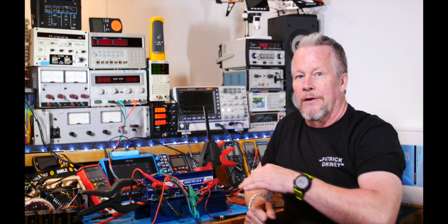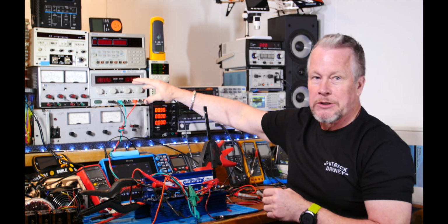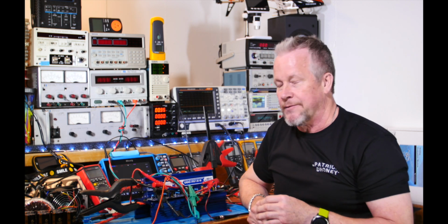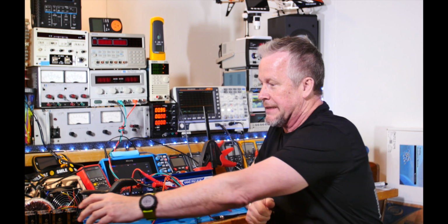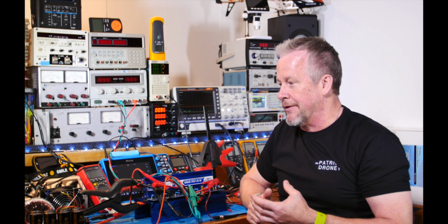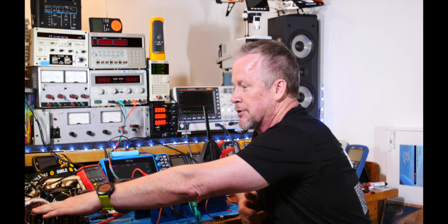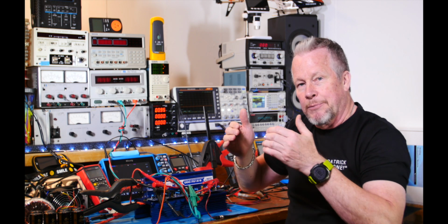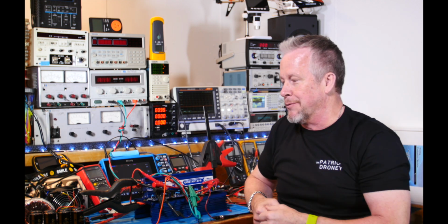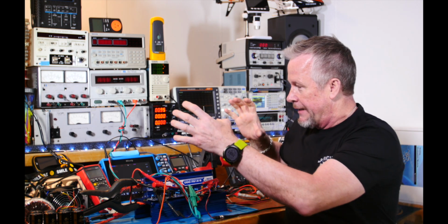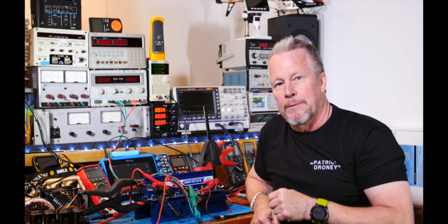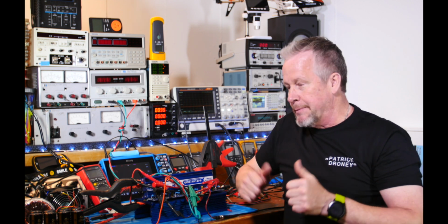So once we get our AC supply hooked up, I could put a bunch of bulk capacitance on the DC supply and improve it, but next video, guys, I'm going to show you another power supply design. It's much like this. It's just another kit I bought. We're going to put that together, and since this one's all put together with all the capacitors, that one I'll put one cap on the bank at a time and then add them, and we'll see how it improves it, okay? But once we get a beefy, stiff, plus or minus power supply on this thing, then we can optimize that bias current, and we should be all good to go.